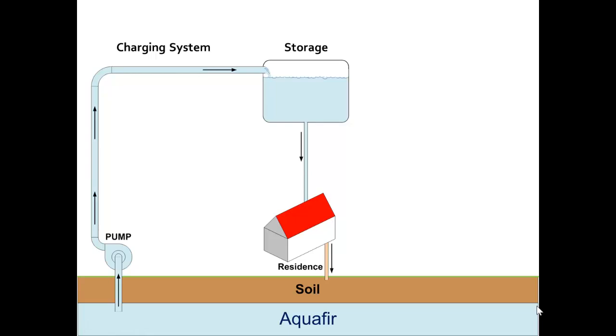So let's quantify our public utility freshwater system here. If we want to quantify the amount of force, we're going to do that in terms of head, and we'll do it in feet. So head pressure is the height of the top of the water column above the point where you're going to use it. And that includes the water in the tank too.